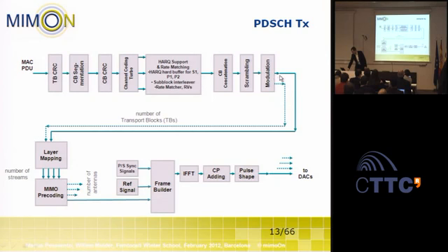In case we have just a single stream that we want to transmit, we have only a single code block, a transport block. However, if we are using MIMO, we can transmit more than one stream simultaneously. In this case, we have another transport block in parallel, which may have a different code rate and also a different modulation scheme, arriving here at this level.